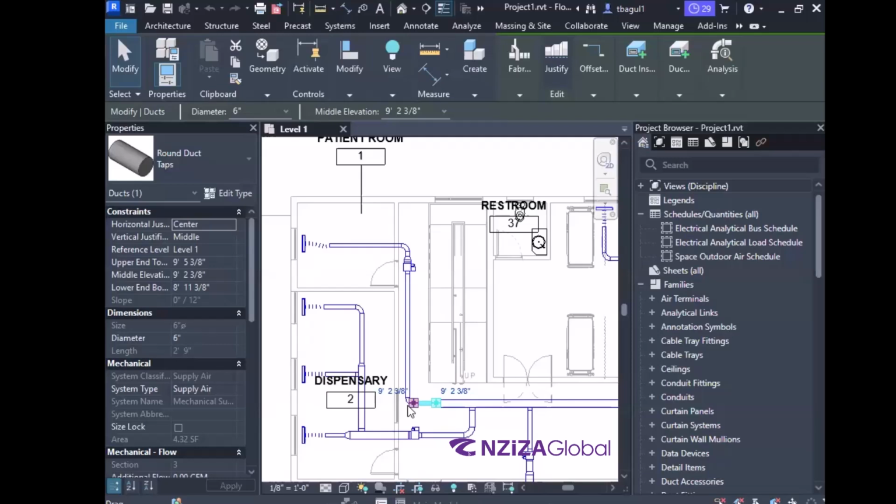Hard surface. So yes, you are correct. There will be a hard surface if you are using something like cast iron duct, if needed, because some of the jurisdictions ask you to do that as well. So in that case, yes, as compared to GI, the upper material will be very rough. It will take up more pressure, right? So it might be somewhere between 0.2 or 0.5 or something like that.